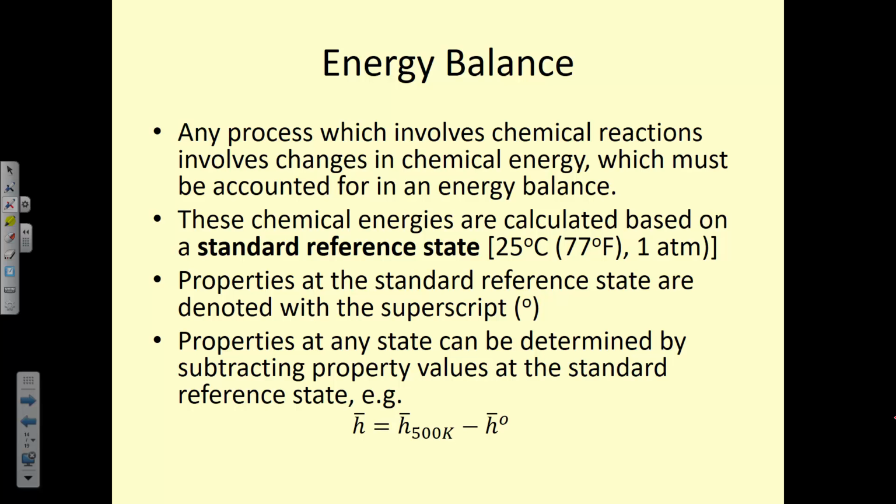And we've seen that before in the ideal gas tables. You remember we have entropy, if you just turn back the previous page, with a superscript 0. That's a reference entropy because we have to take into account how entropy varies with pressure. So this is a similar idea: we're taking 25 Celsius, or about room temperature, to be a reference state in order to calculate all of these entropy, enthalpy, and Gibbs function values, because most combustion processes occur in surroundings around 25 degrees Celsius.